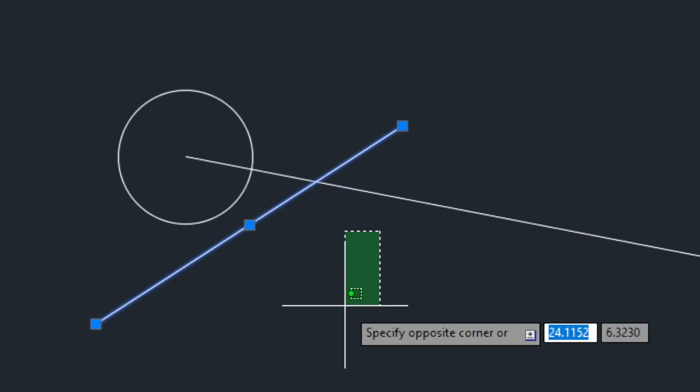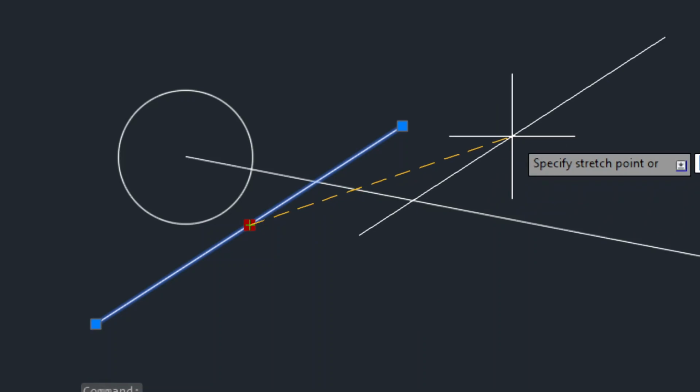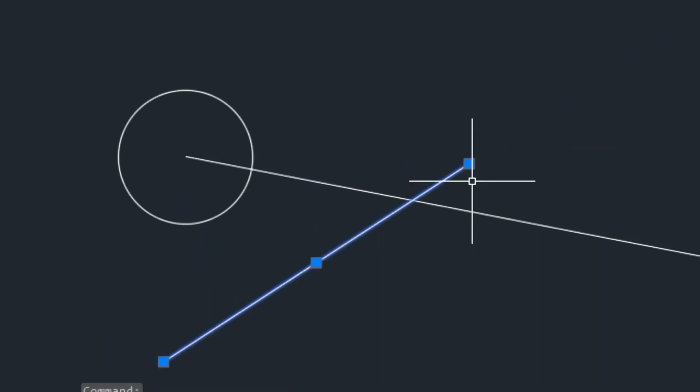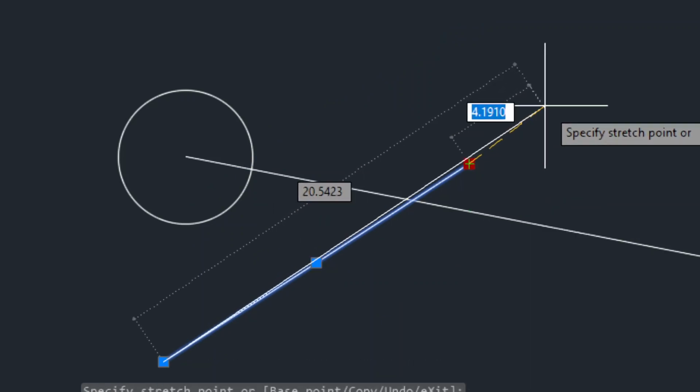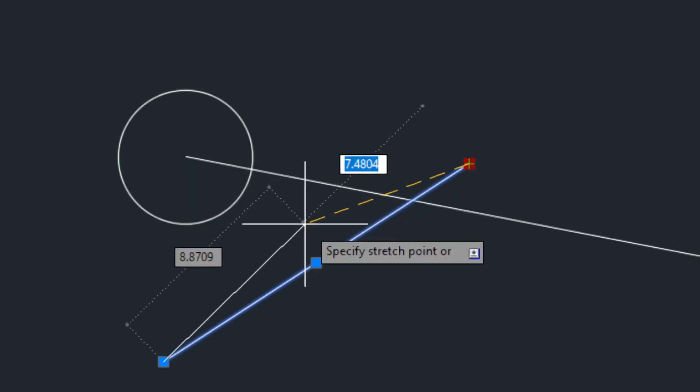So when I click any of the objects, once I click on the object, now here I see the grip, the center grip. Now look at that. This is called a selection cursor. Why is it called a selection cursor? Because once you bring the cursor near to the center point and click it, now I can drag the line from one place to another place. If I drag the corner, I can increase the size of a line or decrease the size of a line.